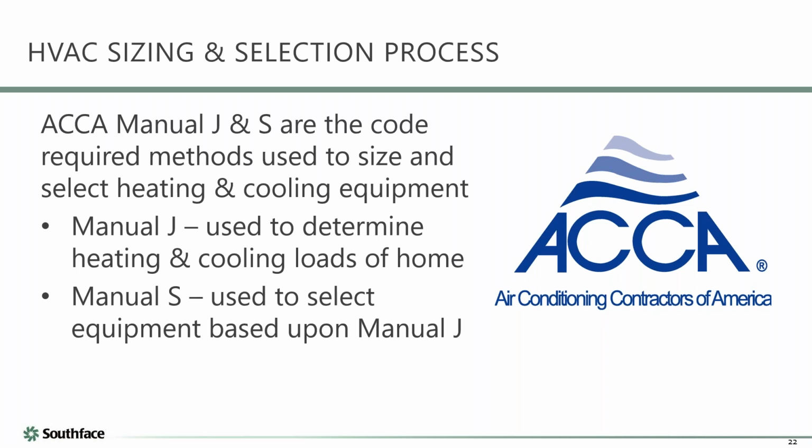So I thought I'd try to give an example, and Joey, you can grade me at the end and see how badly I bomb on this. But let's say that you do a load calc on a house and the summer cooling load is 28,000 BTUs an hour. Of that, we'll break it down: we're going to say that 22,000 is sensible and 6,000 is latent, and that would give you a sensible heat fraction of about 79%.